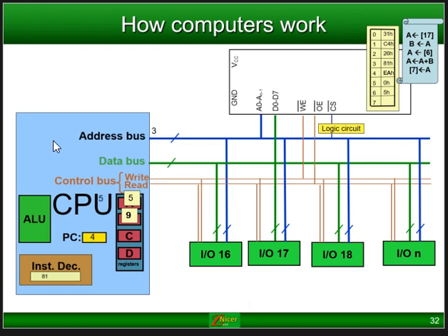And let's execute it. There you can see it's moving 5 and 9 into the ALU. It's adding them, and it's placing the answer in A. So A plus B, 9 plus 5 is 14, and the hex value of 14 is E, and that's why it's being placed into register A. So this is what happened with instruction number 3.